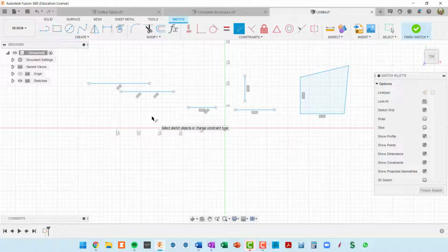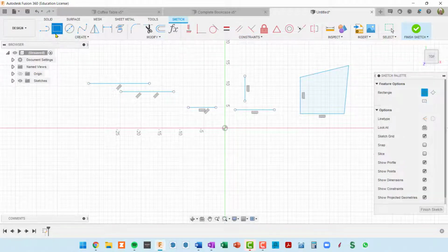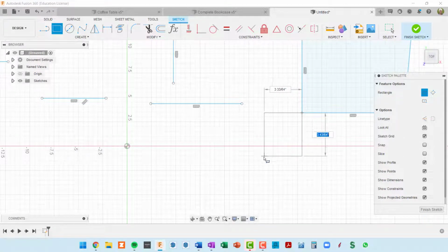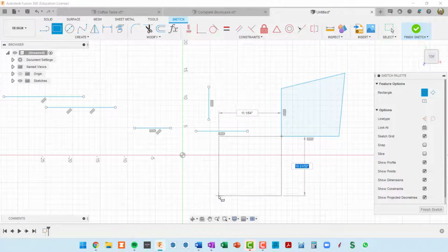Okay, so getting back to coincident constraints and how this stuff gets added automatically to your sketch. Let's say I make a rectangle and I start it right here at this point. You see a blue rectangle popping up. And when you see that and you click there, you are getting a coincident constraint.